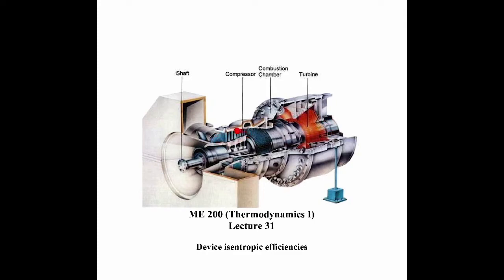Typically, the compressor compresses the material in many different stages. You can sort of see that here, a bunch of different stages in the compressor. The reason it's done little by little is because it's just more efficient that way. We'll talk a little more about that later. Same sort of thing with the turbine stage. You generally want to extract the energy from each set of turbine blades little by little. You'll get more efficiency that way.